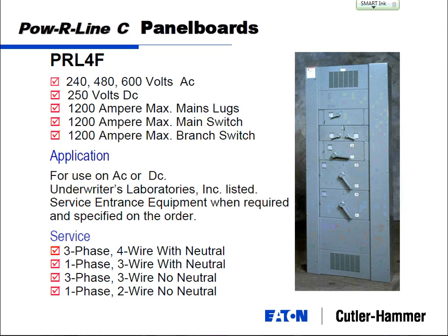Okay, 4F for fusible. Everything else is the same. It's just a matter of fusible switches versus circuit breakers. And you can see this one might be a 400 amp fusible switch. Fuses inherently are bigger than circuit breakers. So when you're talking a space savings design, a panel board or switchboard that has breakers may be half the size of one that has fusible switches, which is another reason why folks are all moving to circuit breakers instead of fusible switches in panel boards and switchboards as well.